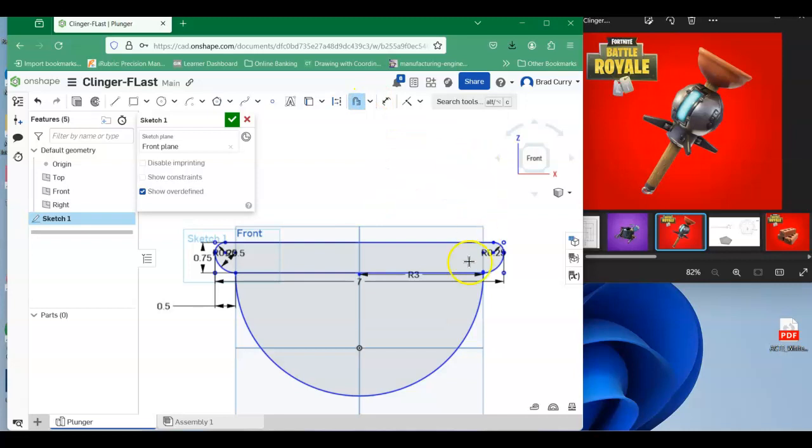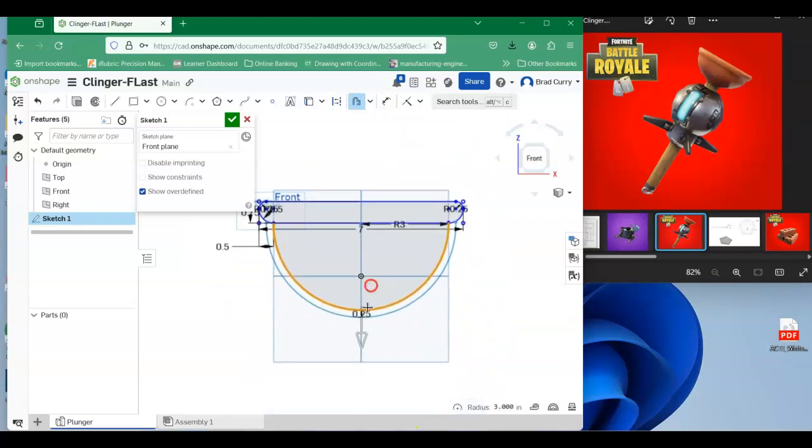Let's offset this radius. Let's go the other way, but let's make this 1 inch. See if it'll like 1 inch. Yeah, I don't like that. That's a little extreme. So let's hit escape to get out of the offset. Let's double click this and make this 0.75 on the wall. That's a little bit less extreme.